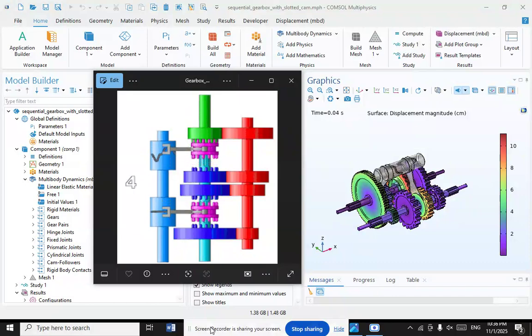This restriction avoids accidentally selecting the wrong gear. However, it also prevents the driver from deliberately skipping gears. The use of dog clutches rather than synchromesh results in faster shift speeds than a conventional manual transmission.